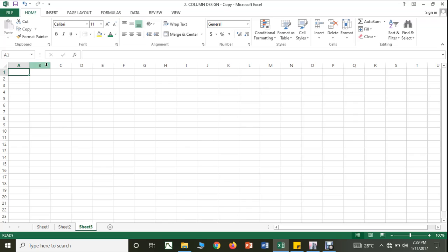So let us make a group number 1. So this is group number 1 of 230 by 460 dimension, and the diameter is 20 mm, and I need 8 bars, and the lateral spacing is of 9 inch, right?